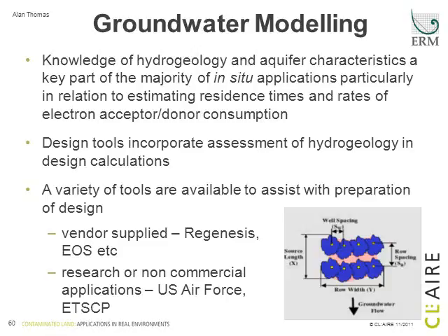Groundwater modelling can form an important part in in-situ bioremediation design as well. As is apparent from my preceding discussion, knowledge of the hydrogeology and aquifer characteristics is a key part in in-situ application. There are a variety of design tools that incorporate the assessment of hydrogeology in design calculations. A number of these are vendor supplied, and a number are research or non-commercial applications.